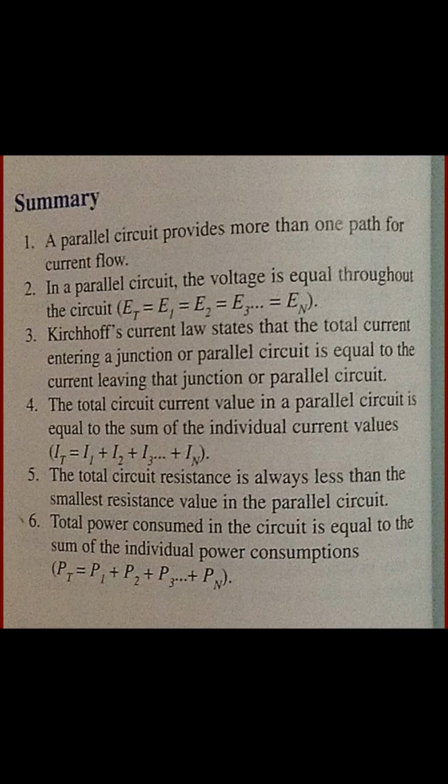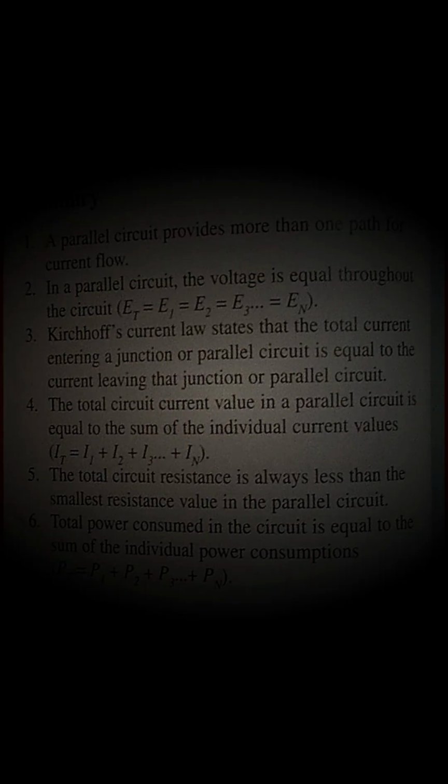The total circuit resistance is always less than the smallest resistance value in the parallel circuit. That's an important point to remember. And the total power consumed in the circuit is equal to the sum of the individual power consumptions, like power total equals power 1 plus power 2, and so on. Remember, power is always measured in watts.